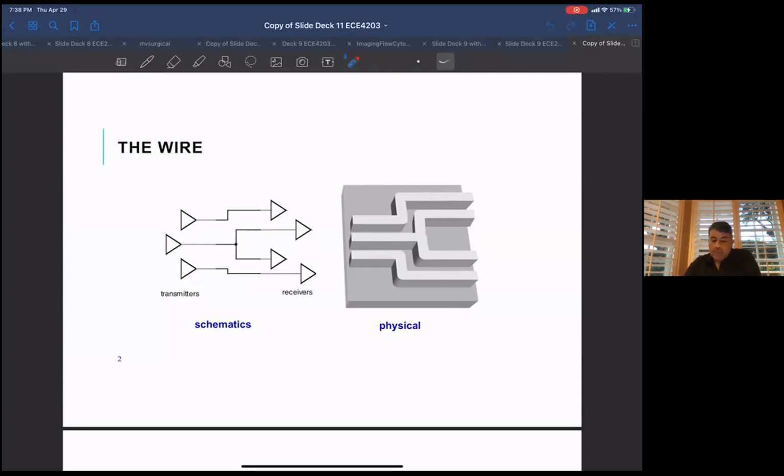So far we've been talking about the transistors only. In the case of the rise and fall delay, we've said we're only going to consider the input gate capacitance of what we're driving and the drain capacitances of what's driving it.